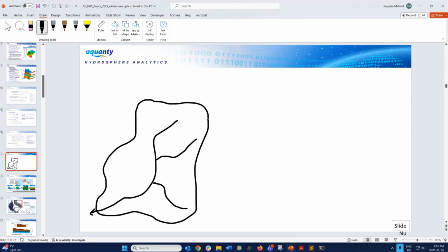Maybe you build yourself a watershed scale model, but you're really mostly interested in evaluating hyporheic exchange or something on a stretch of the stream. So this can be, we'll call it L, and we'll call this larger one R. You can run a regional model and then use the results of this regional model to define boundary conditions around the edges of your local model, right?